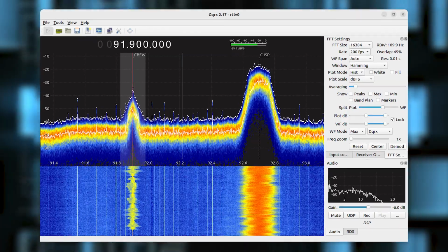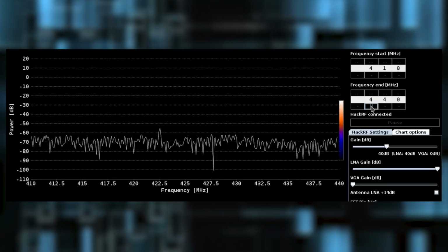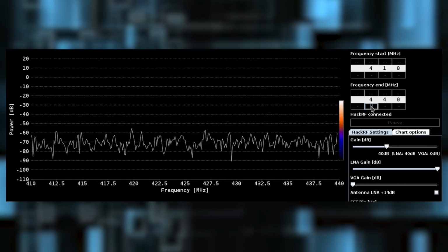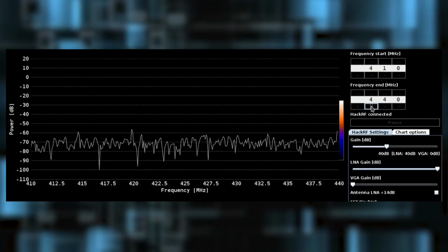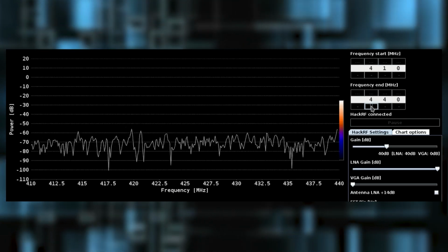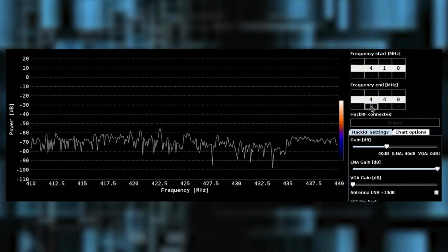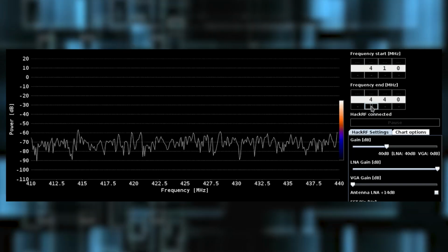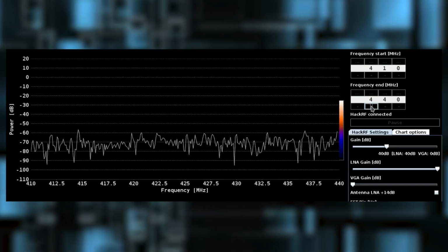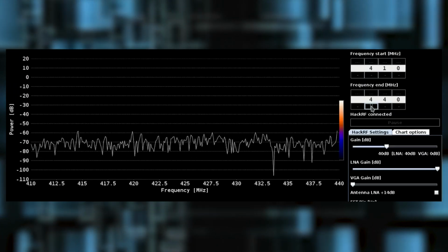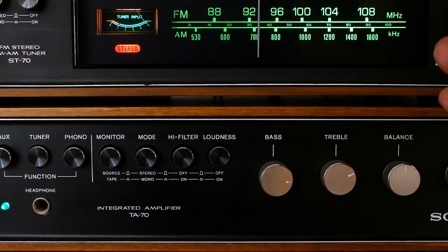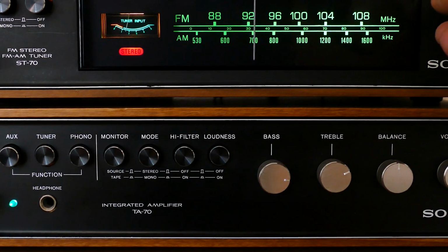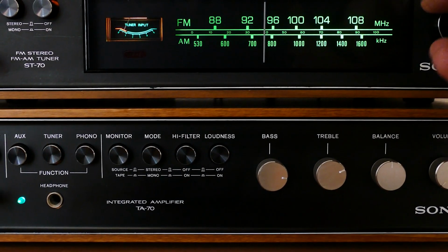Now, in regards to exploring radio frequencies, use GQRX or SDR++ to scan and analyze radio frequencies from 30 MHz up to 6 GHz. Okay, so after that, you're going to want to experiment with receiving various signals such as FM radio, amateur radio, or even key fob transmissions.